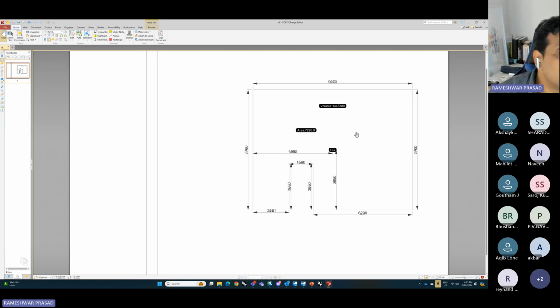But imagine you have 100 panels, 200 panels, and so on. The drudgery of modeling each panel separately and then linking and maintaining that mathematical accuracy with your SAP2000 model, and then maintaining the physical accuracy with Tekla. Everything you are controlling through one model source. So you model all the panels in Rhino and Grasshopper, you link it and generate these drawings. You link it to SAP2000 and you link it to Tekla Structures as well.